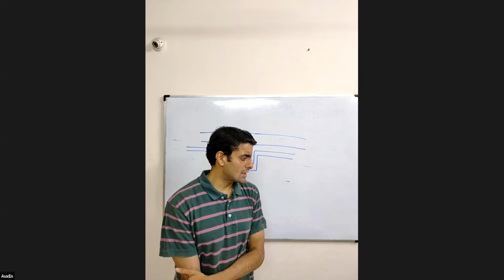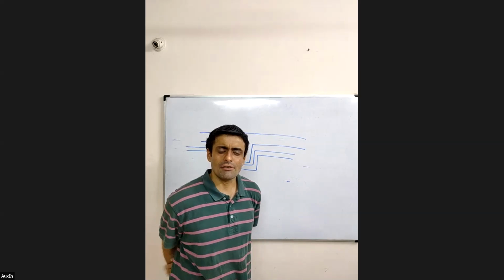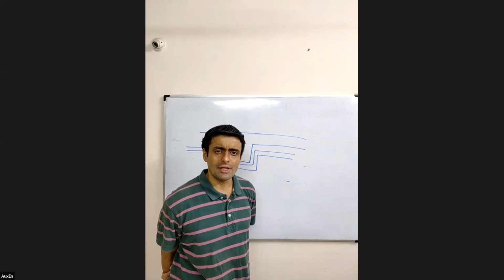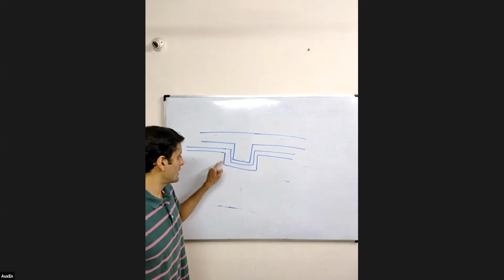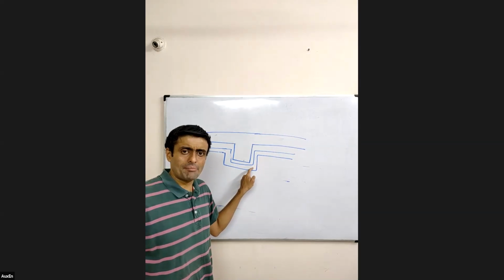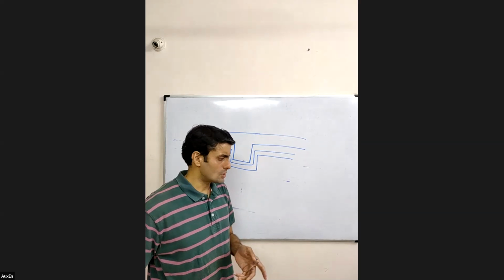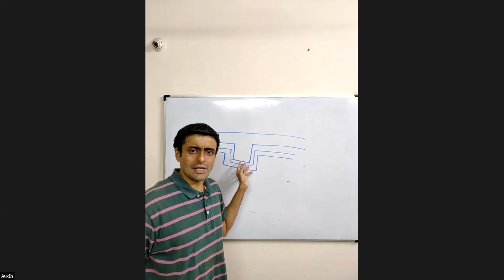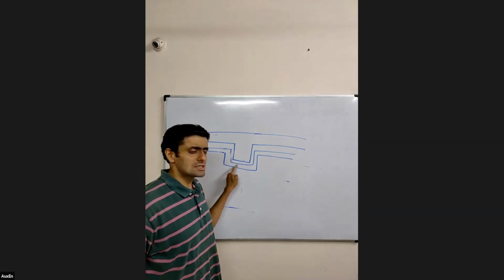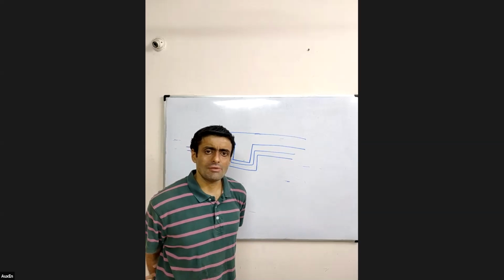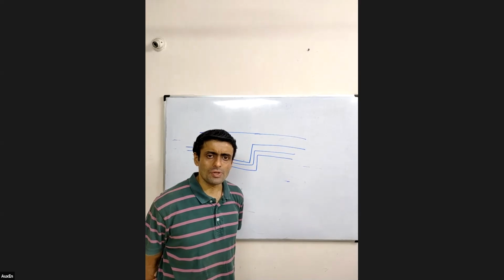But if these are lines with some pressure in them, let's say firefighting water lines or air conditioning coolant lines, then a sudden dip in your pipeline may disrupt your pressure calculations. Your designer for plumbing or service lines may not allow such a sudden dip in pressure. So this is also not a possible solution.